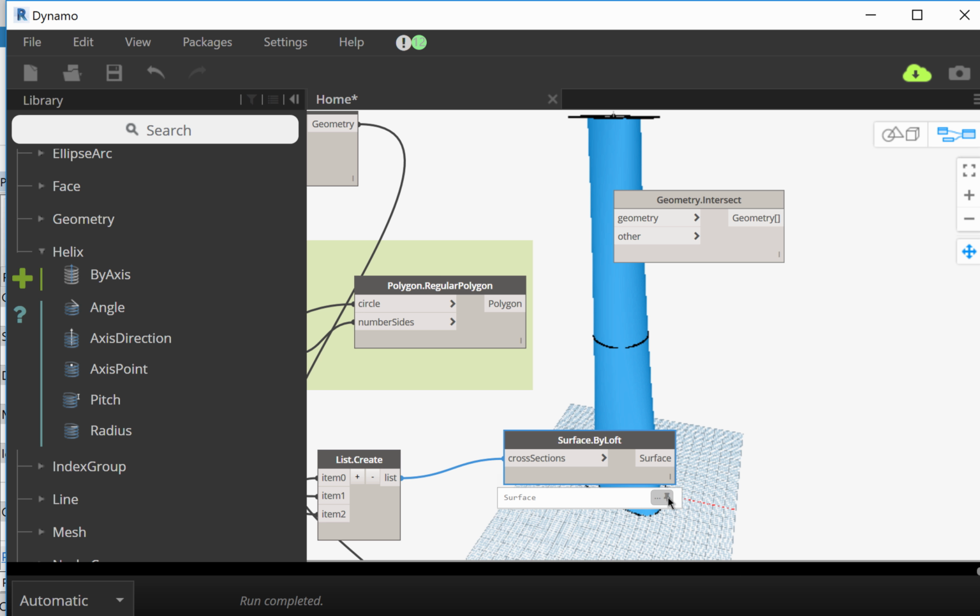And I'll tell you something. Surfaces in Dynamo sometimes cannot be directly imported into Revit because Revit is a little bit limited in the computation of very complex deformations. One of the ways to solve that is to make the surface become a NURBS surface. Are you familiar with that term, NURBS surface? It's very typical in Rhino.